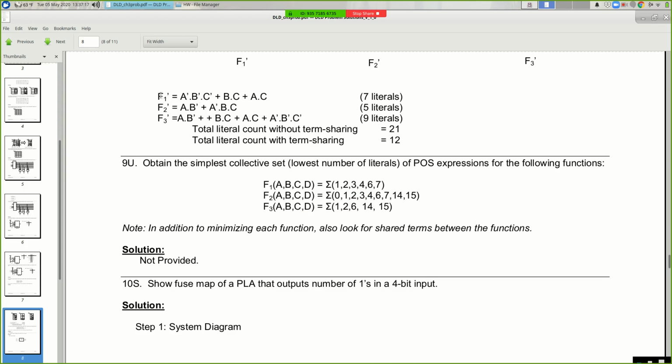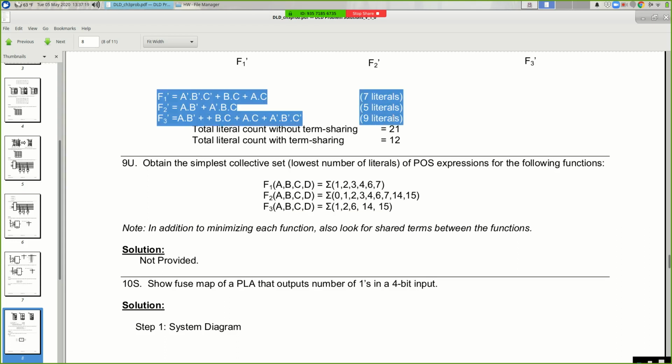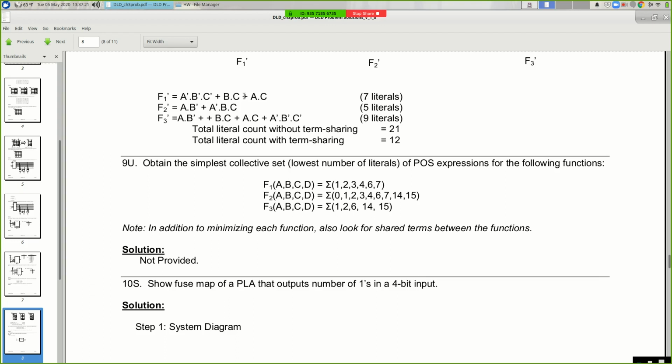Okay, so you can calculate two things. For example, in this example, the solved example, f1 had 1, 2, 3 things it had to calculate. f2 had 2 things. f3 had 3 things, right? But you can share some of these expressions. For example, b ANDed with c is used in both f3 and f1. Okay, so you're just doing some analysis, looking at how many unique terms you have, how many terms you have total, and how many terms you actually share from one expression to another.